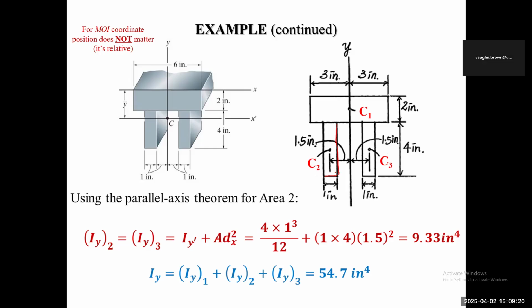All right, let's find I2. See, I'm showing you here. Let's find it now. This one is with the standard formula, which is bd cubed upon 3. So if you want to call that b cubed, fine, and you call that base 1. Or if you just want to switch them around and say that this is the base, that is the height, so you know this distance here is cubed, and that distance is h. It depends on how you want to remember it. All right, so here they have it for the first part.